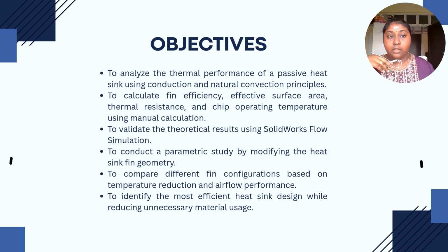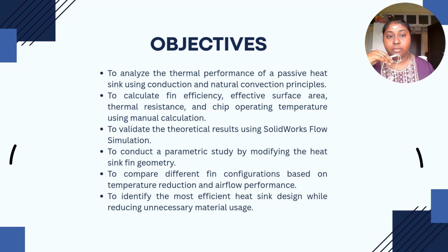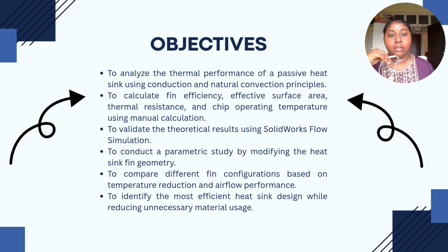There are 6 main objectives for this project, which is to analyze the thermal performance of a passive heat sink using conduction and natural convection principles. Next is to calculate fin efficiency, effective surface area, thermal resistance, and chip operating temperature using manual calculation. The third is to validate the theoretical results using SolidWorks flow simulation.